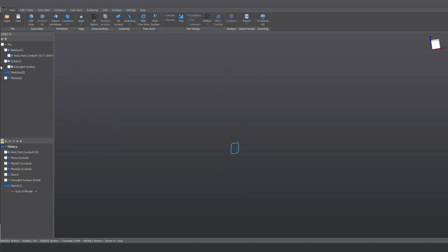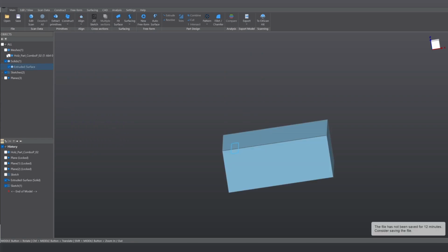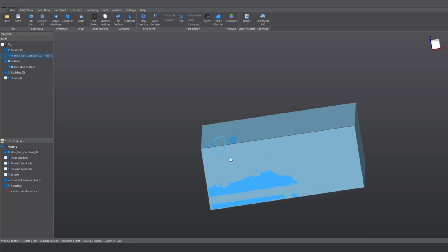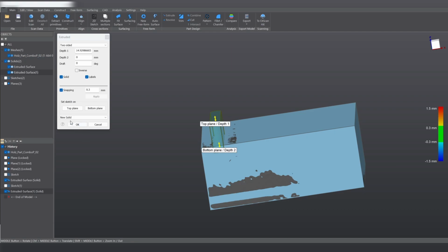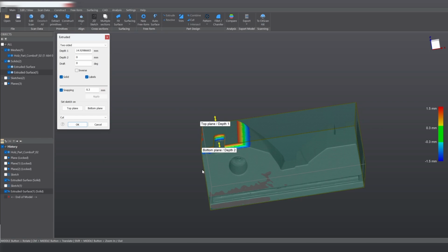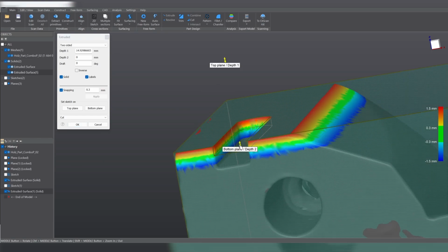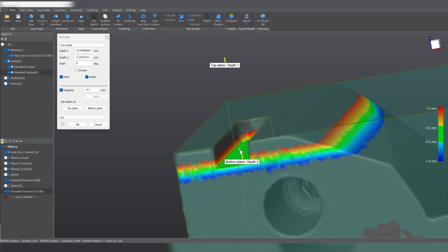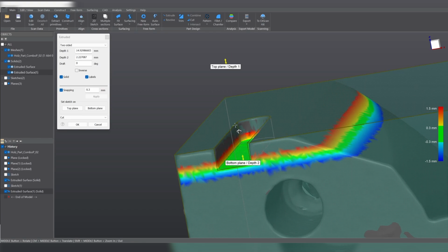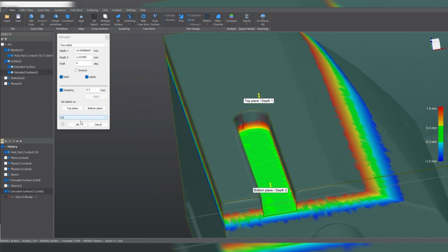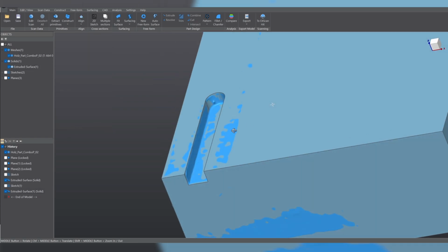Now we need our solid body and our STL file. Click again on our sketch, go on extrude, and here, first set of new solid, we go on cut. Our solid body got transparent, so we can see what will be cut. And also here now I get a feedback from the STL on to which region I need to cut. This looks good. I click on OK and have here now my slot.